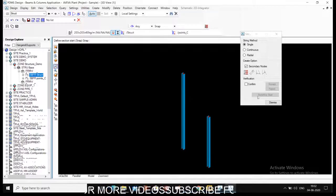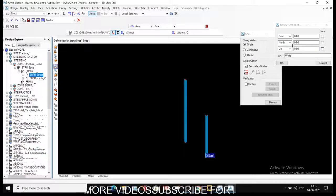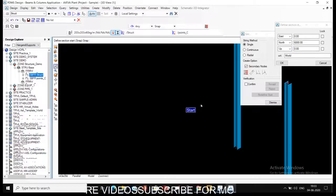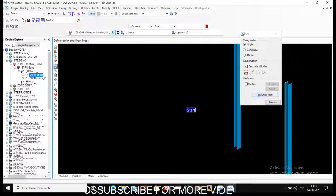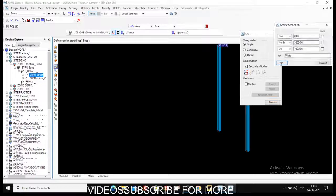Okay, now let us find this redefine start option again. I am just creating again a structure. I am going back to origin, let us say, and I want to give in north, let us say 3000. I have already done that, so I will go with 6000, and by mistake I have defined the start wrong. So what I can do is I will just say okay, and I can go with the option of redefining the start. That will vanish that point, and you can again go with the explicit option 0 0, and in north I will go with 6000.